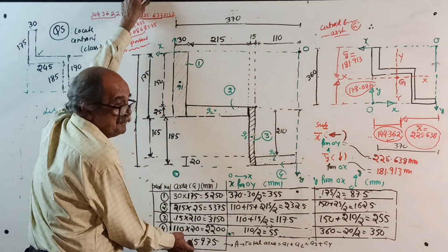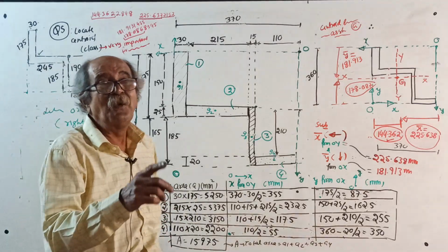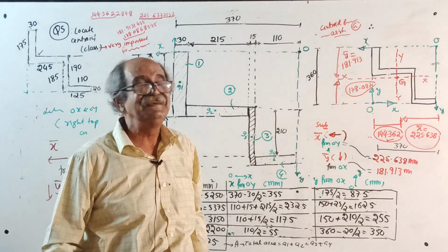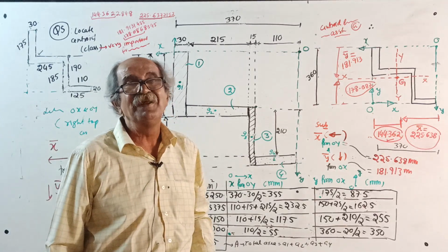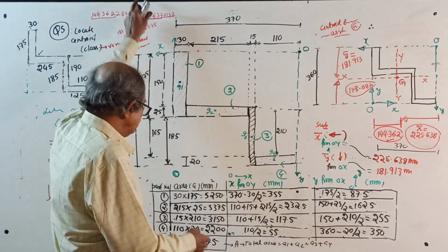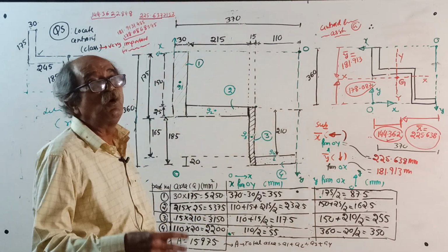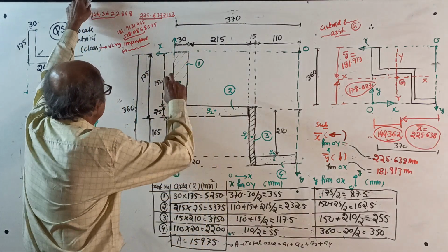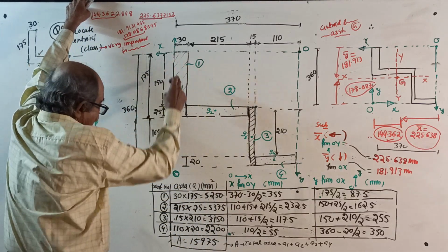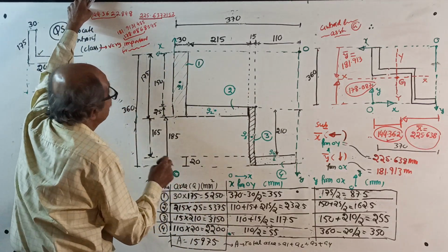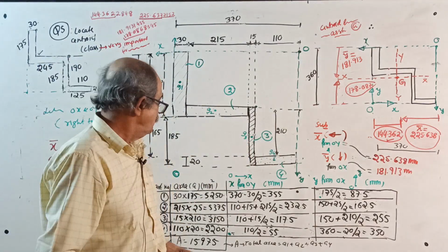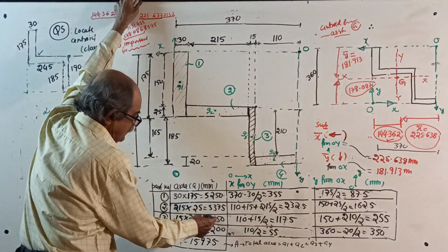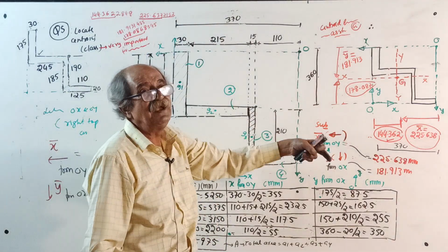The total area will remain the same, but the component areas will change. The total area will come the same, so I thought it was already accounted for. I forgot to change that component. Earlier it was 150 by 30. Now it is 30 by 175. In the same way, dimensions are changing everywhere. Because of the small error in areas, it was not giving the answer.